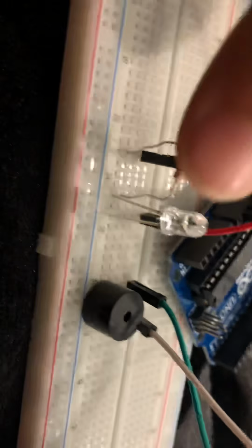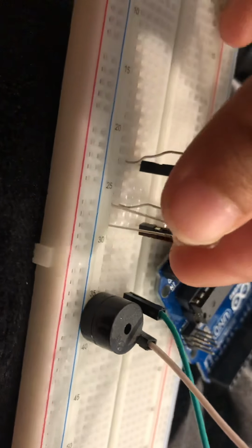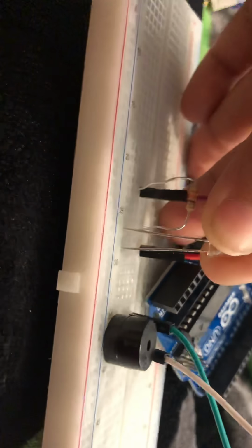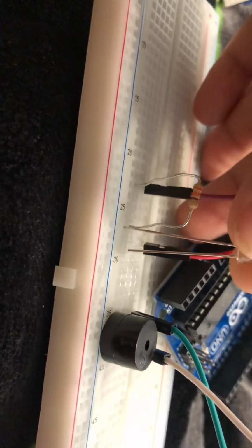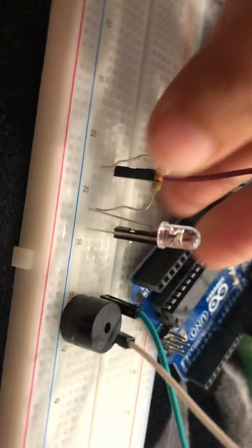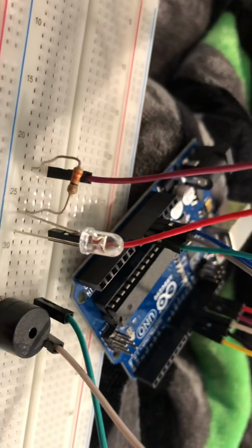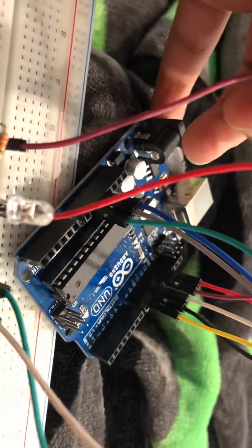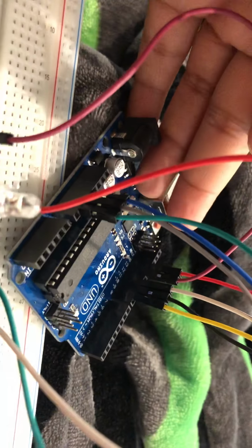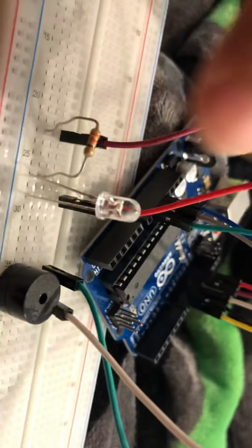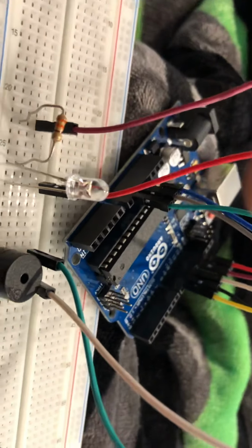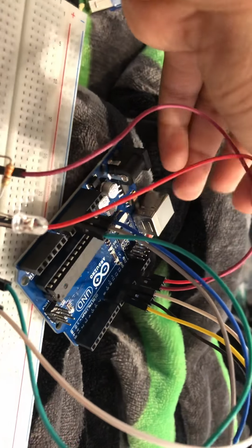And then I have got an LED here. The LED has just one negative terminal and one positive. So I've got the positive over here with the resistor, and this resistor is connected with the pink wire that is going straight over there to D13. And then the short leg is connected to this red wire, which is going straight to ground.